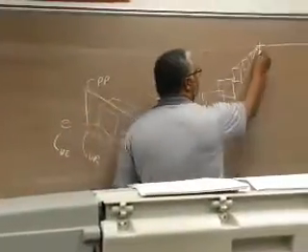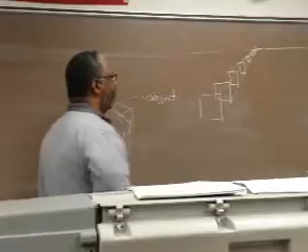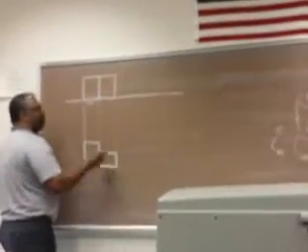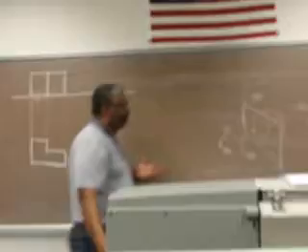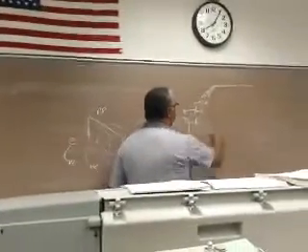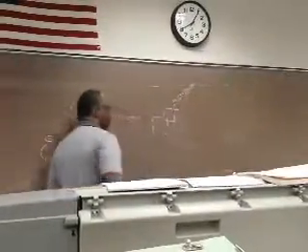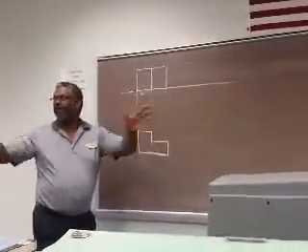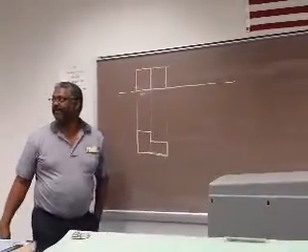The point at which it vanishes is your vanishing point on a 1 point, and it sits on the horizon. So if the vanishing point changes or the horizon changes, it will change what the perspective looks like. So we had you lay it out based on the values given, so everybody's perspective should look the same.